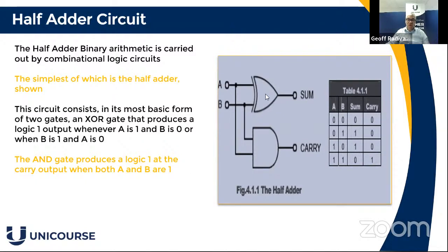Now, I suggest when you are looking at something like this, just look through it, reflect, draw it out, and think it through, and get it in your own mind how you see the circuit works, even to a degree by either drawing it out and producing the truth table, or using a simulator to actually try it out. So here we have the truth table to our right, as I've said, and that is the half adder circuit.